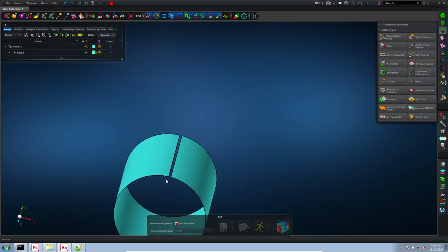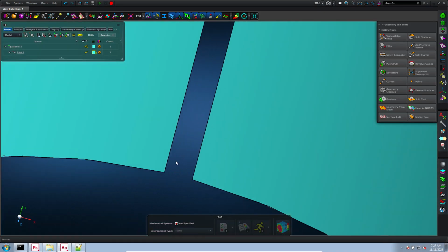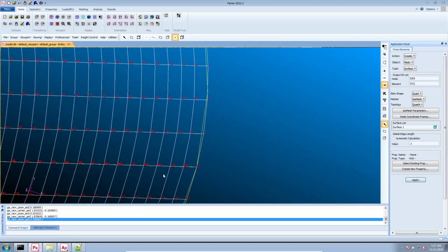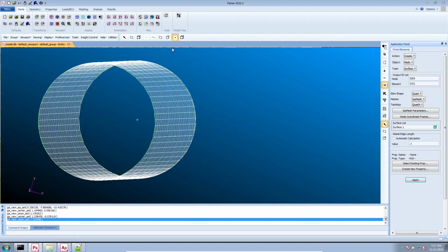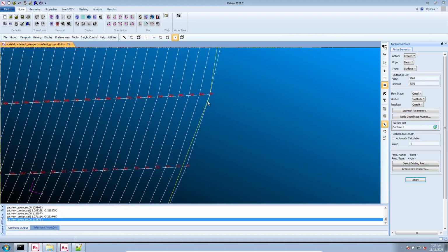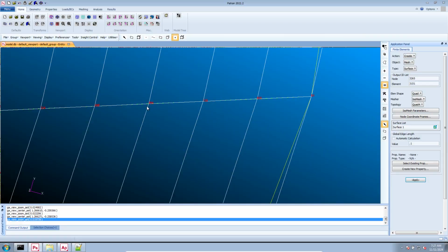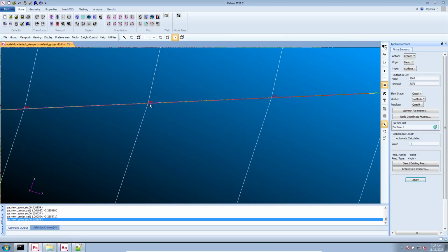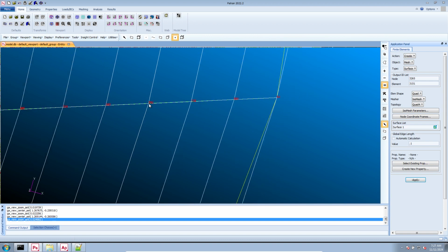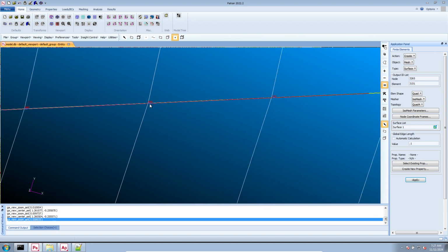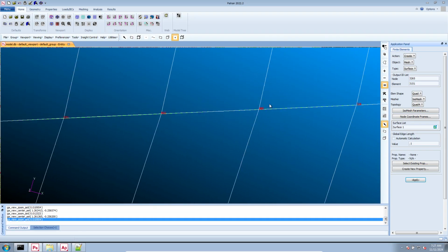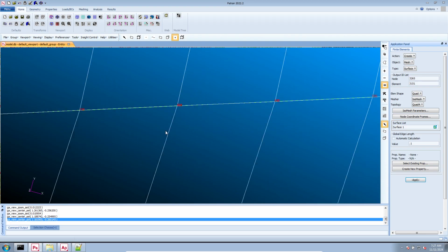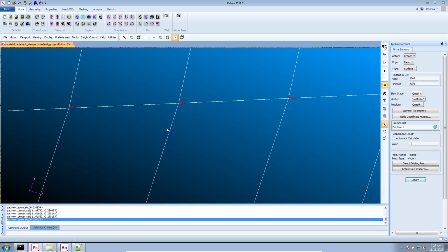And think back to the geometry in Apex. Here, the crack is noticeable. There is some non-zero distance in the crack. But here in Patran, when you build your geometry, from far away, it doesn't look like it has a crack. But if you look at the node numbers, and if you know where to look, you'll actually see that there are overlapping nodes. Here, look closely, none of the node numbers are legible. Here, you're not sure if it's node 298 or some other number. If you move this a little more, you'll see the same. None of the node numbers are legible. This is evidence that you have overlapping nodes.